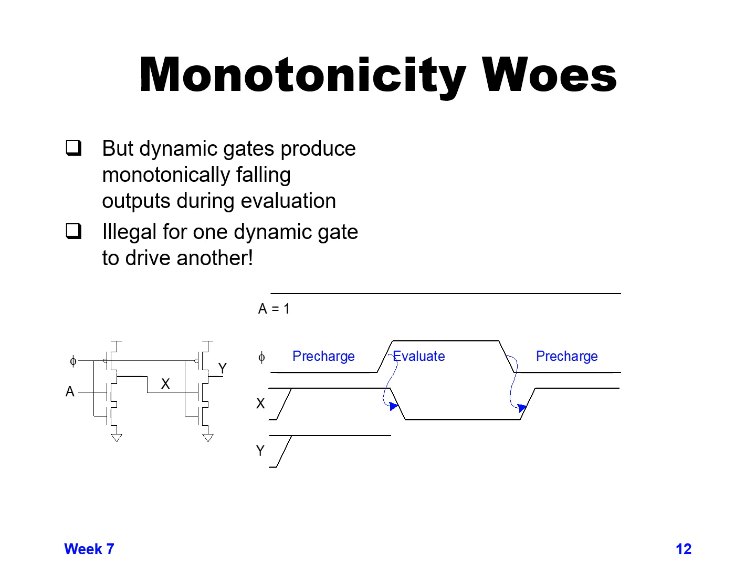So as I said in the previous foil, we have to make sure that we do not allow a 1 to 0 transition at the input of a domino gate during evaluate. So what happens if we have one domino gate driving directly into another domino gate? You can see down below, if we have two domino inverters, one driving the other, we will get a problem. And I'll go through what.